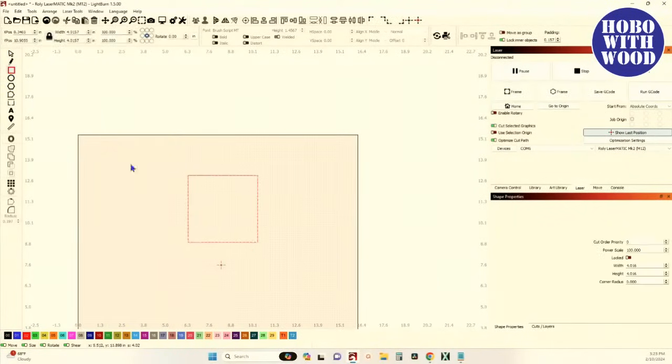But prior to this scalable radius, the way I was doing things would be like, okay, if this is a 4-inch square, give or take, and then in fact, we'll just make it 4 inches. Then I knew that if I wanted my radius to be just shy of center, I would select the radius tool and tell it to do a 2-inch radius. Then it's going to start at about 2 inches in and come down, and it's going to create almost a circle if I do radiuses.